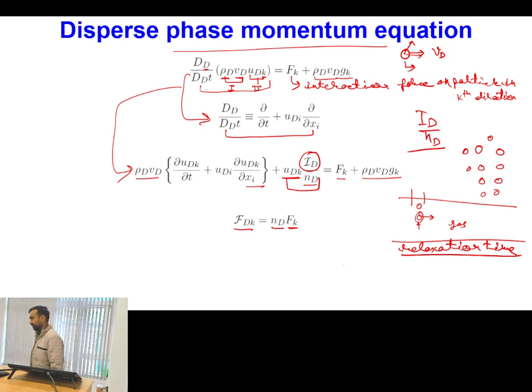But if the relaxation time is more than the time scale at which fluctuations happen in the velocity field of the surrounding phase, the particle will lag behind the changes in the fluid motion, and most of the time it will remain in a state of acceleration or deceleration. Is this point clear?